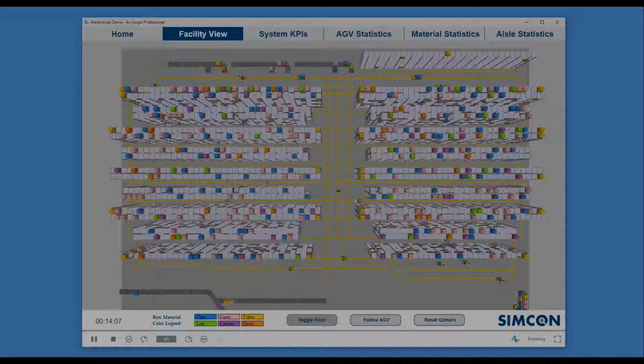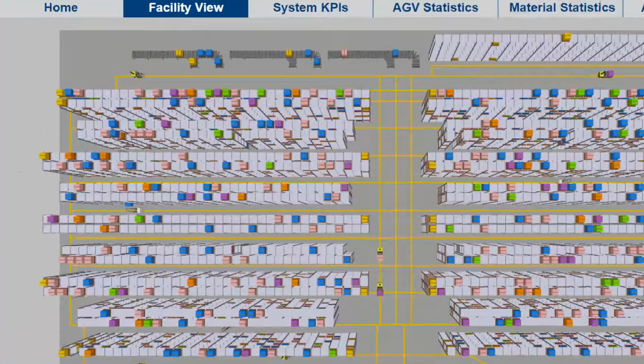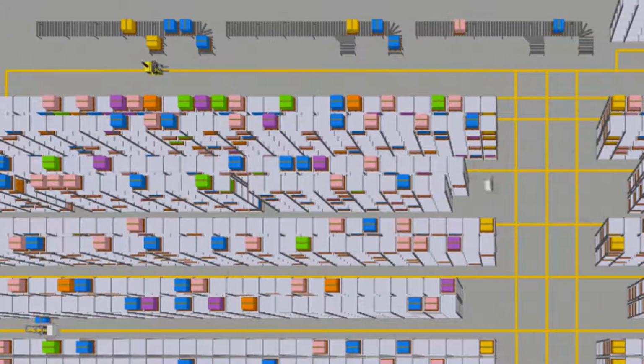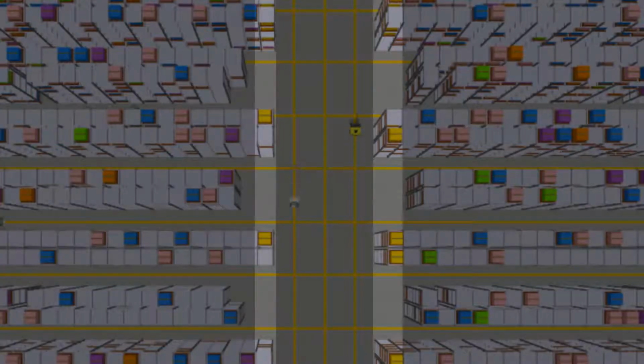So the basic flow in the system: pallets from receiving arrive at these transfer conveyors up the top of the facility. So from the north side of the facility, they're checked into the WES system, and then these yellow CB12 AGVs transfer them from those conveyors to the pick drop locations, and then the V&A picks them up from there and stores them in the pallet racks.